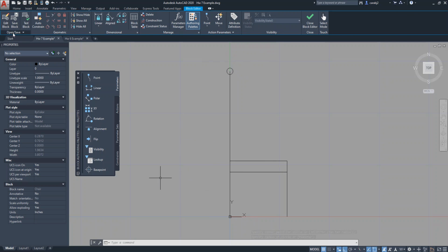So then here on the side, I'll walk you through here. You can edit the block, that's what we're doing. Saving the block, so self-explanatory, you would save everything that you make. Testing it means it would just open a window to test the block within the drawing. And then this here is basically all the geometric functions that you can put into your blocks. These would get a little bit more complicated, but it would be helpful for blocks that are more parametrically constrained.